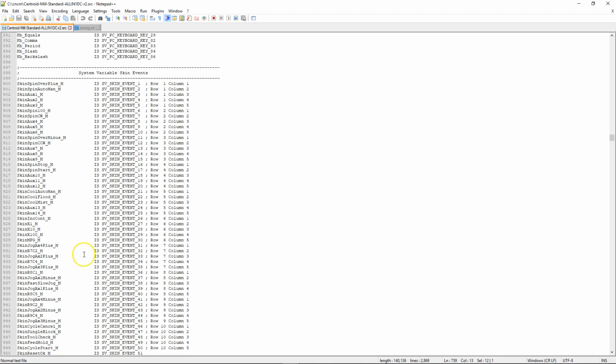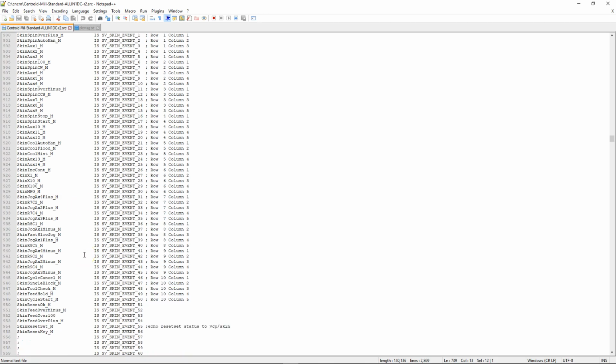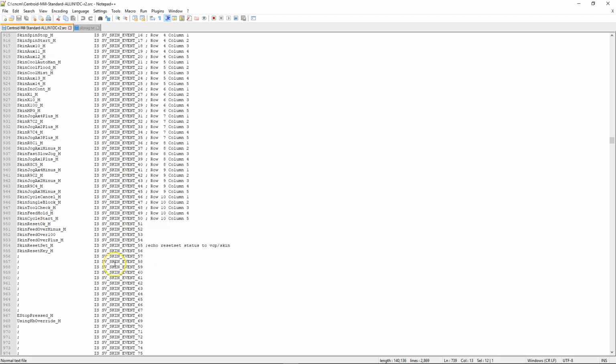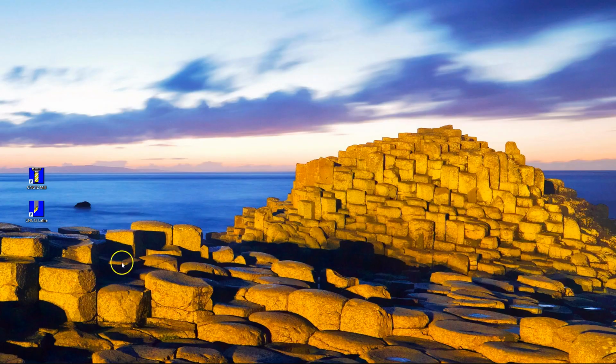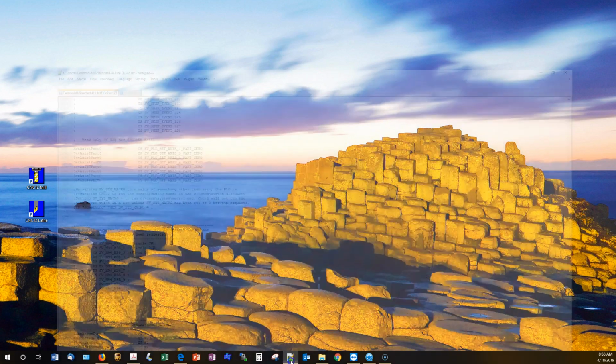And that is also one of the reasons why anyone that upgrades from an older CNC 11 system to a CNC 12 because they want to add that feature of the virtual control panel, well, if you don't have the PLC program appropriate for that, yes, you might see the virtual control panel on the right-hand side, but whenever you click on a button, nothing will happen. And that's solely because the PLC program hasn't been modified to be able to handle that. Okay, now back to the PLC.